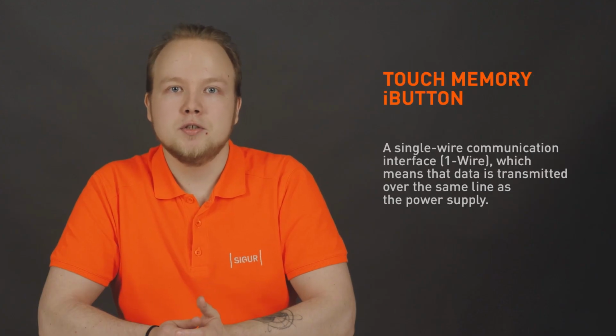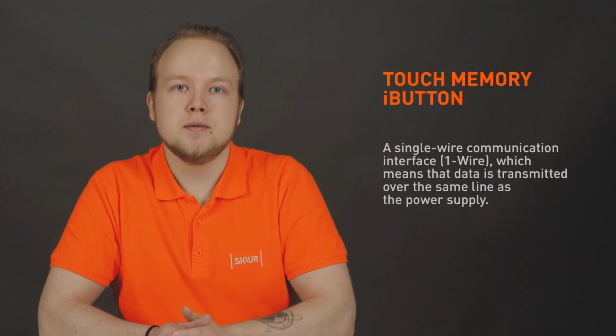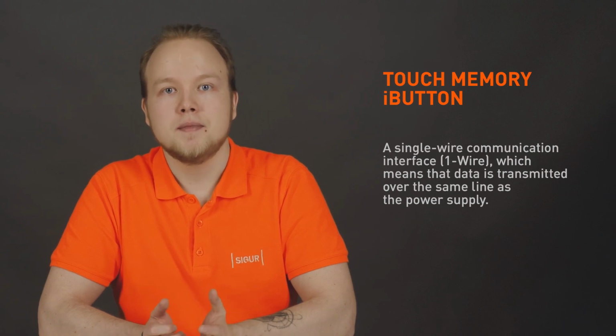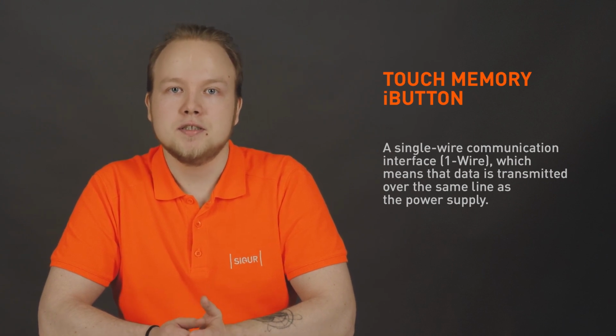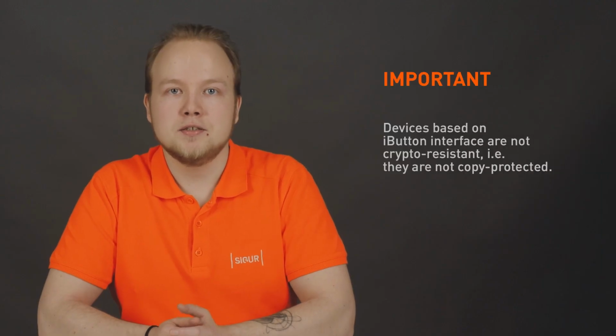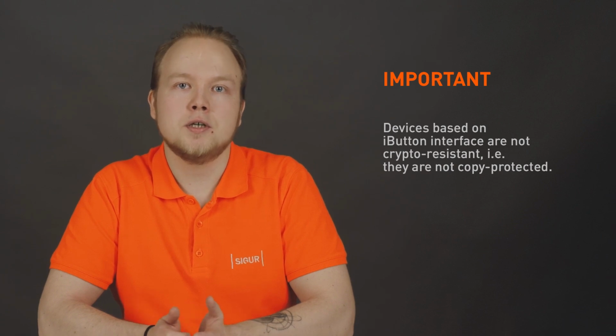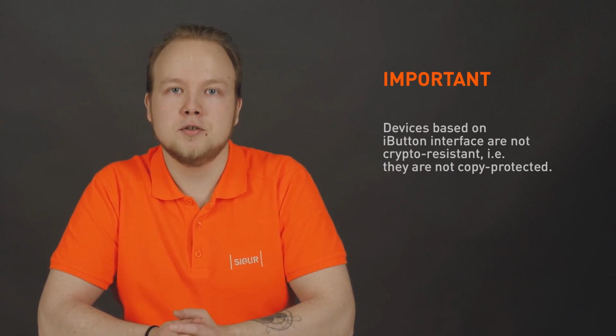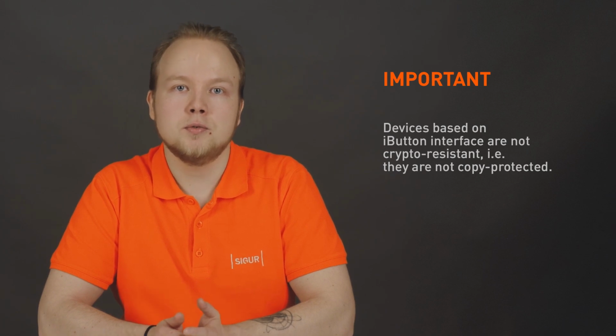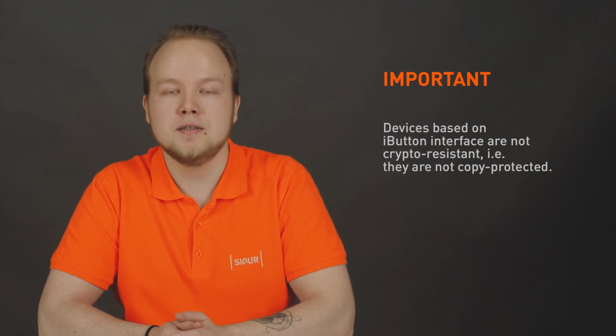Historically, the first devices of this kind were readers with iButton and touch memory interfaces. These are a separate class of devices with a single-wire information exchange protocol known as one-wire. When using this interface, reading the unique identifier occurs at the moment of physical contact between the key and the reader. In other words, these are literally contact keys, with the simplest example being intercom tablets. It was thanks to such technology that the capability to control key retention by the reader initially appeared. However, devices based on the iButton and touch memory interfaces are typically not cryptographically secure, meaning they are not protected from copying and do not have the ability to operate in a secure mode, so it would be rational to use them only if there are no high security requirements at the facility.